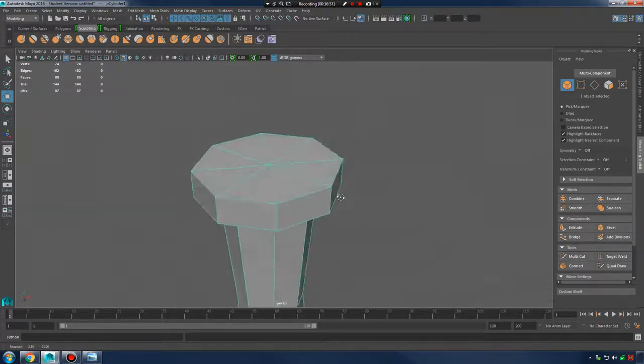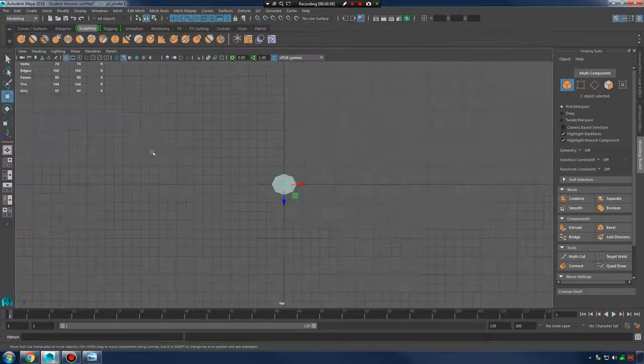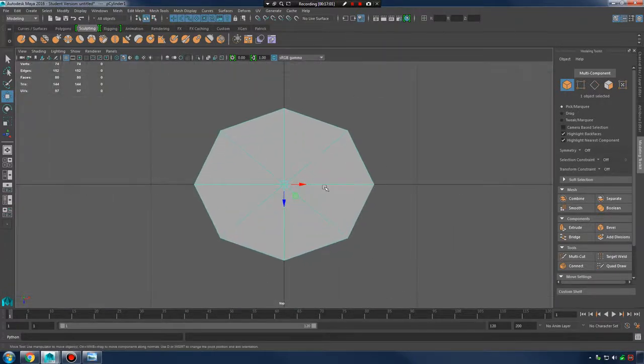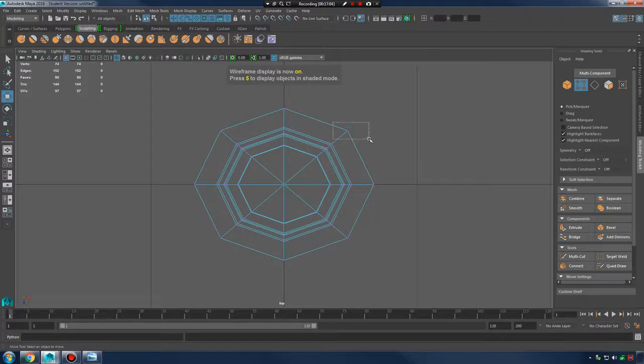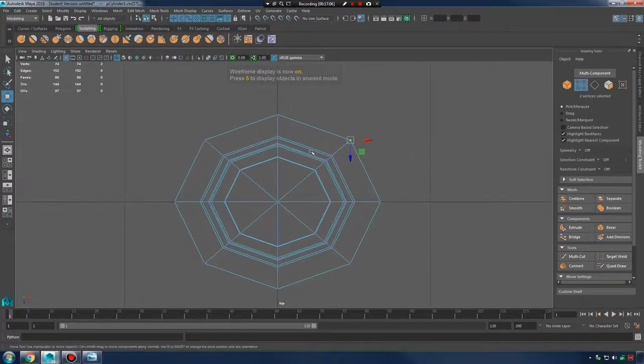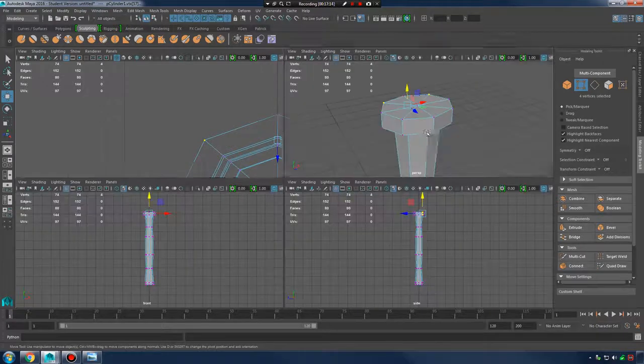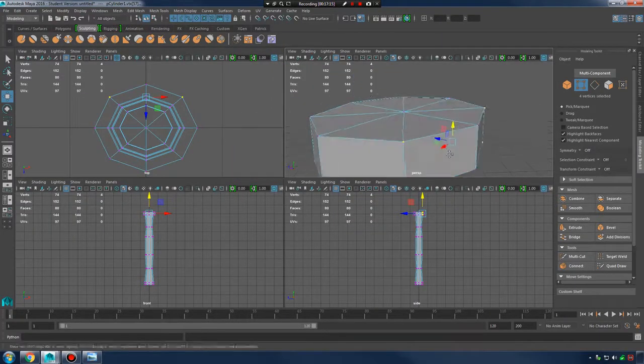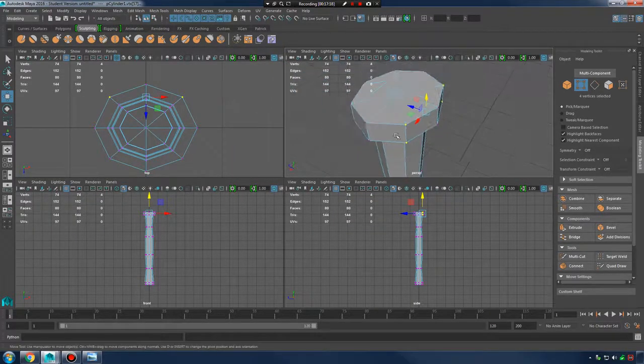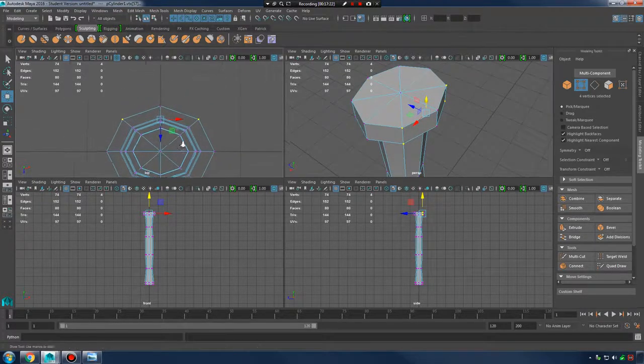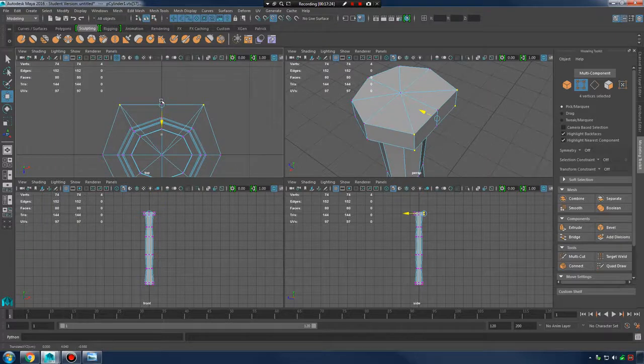Well, now here we're going to use the power of snapping by going up to my top view here. I'm going to select vertices, and we're going to snap them to create our rectangular shape. So I'm going to focus on these two top vertices right here. Be careful not to select any other vertex. And I'll go into perspective mode so you can see what I'm doing. I'm getting these middle two sets of verts, so 4 verts altogether. And then I'm just going to snap them straight up there.